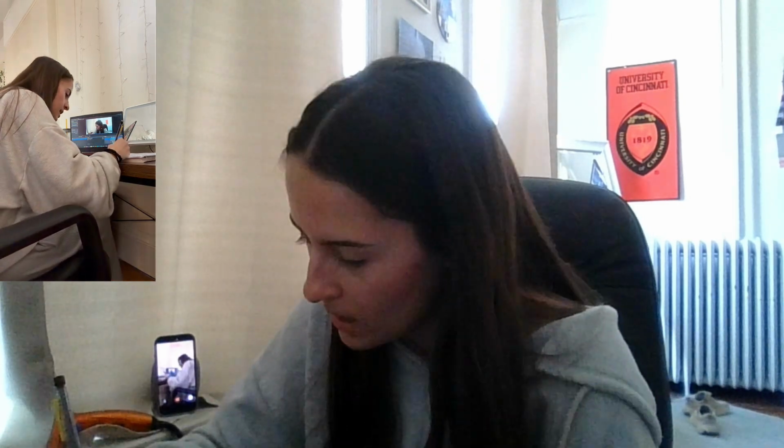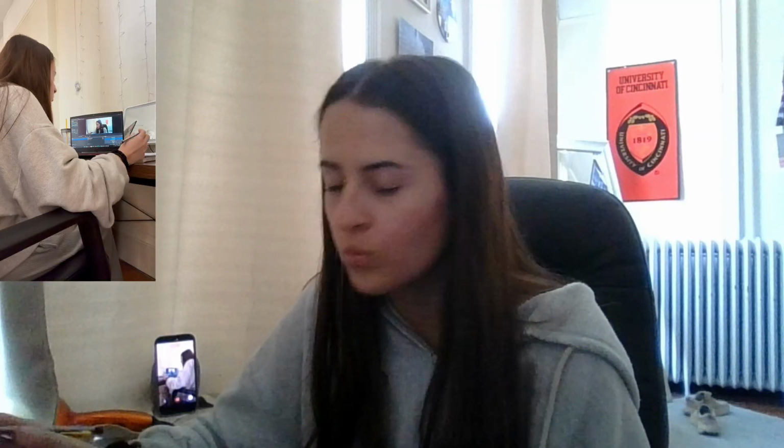So then you'll have H equals 0.332. We have density will be to the 1/2, velocity will be to the 1/2. But now we have the length to the 1/2 divided by length to the first. So that means that we're going to have length to the negative 1/2 power now. So that'll be length in the denominator to the 1/2. And then for our mu, which is our viscosity, we'll have it in the denominator, so it'll be mu to the negative 1/2 times mu to the 1/3 in the numerator. So if we find common denominators there, that's essentially equivalent to mu to the negative 3/6 times mu to the 2/6. So that'll become mu to the 1/6 power in the denominator.